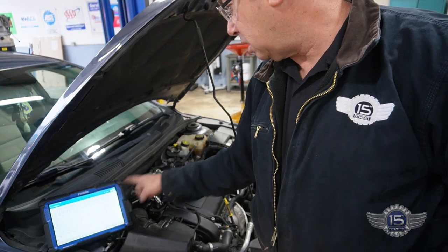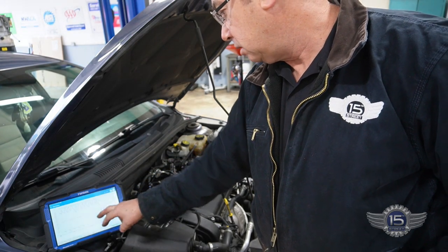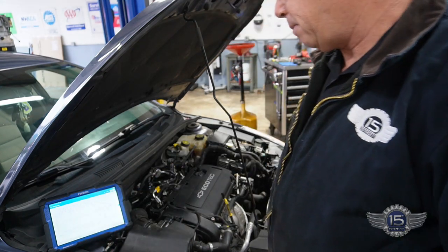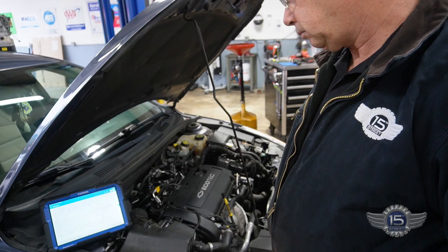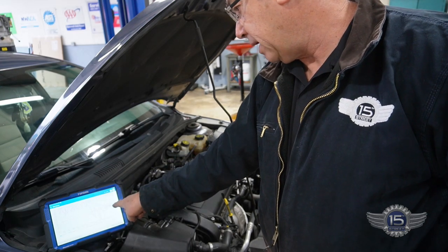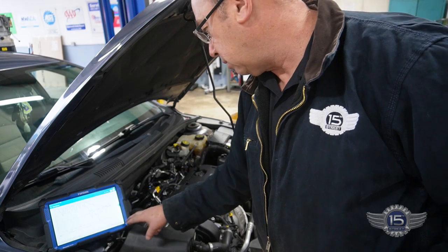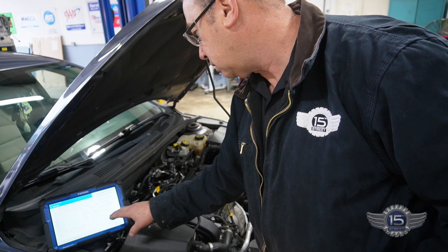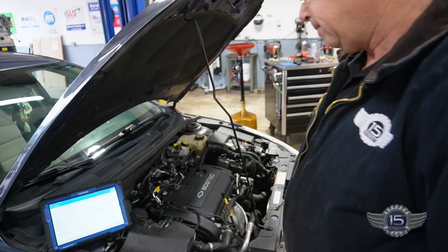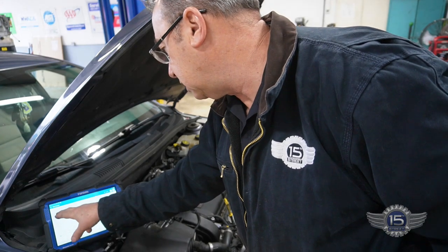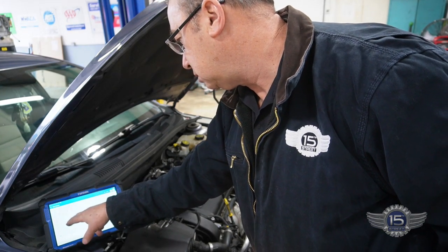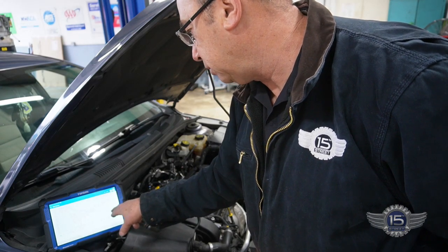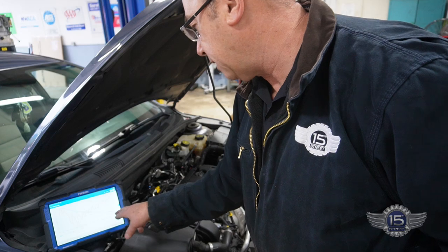With the purge unplugged, it's dropping like a rock. We're already down to 16% at idle, dropping. That's the blue line here. See, it's dropping down. Let me get rid of my mass airflow and clean this up a little bit. So the scaling is, the orange is short term, and this line here is 0, so it's staying below 0. Now our blue is down to 5%.